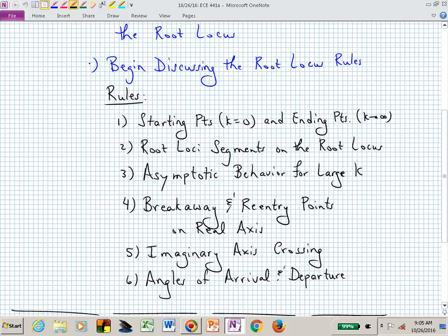Obviously, if branches go into the imaginary or into the right half plane, at that value of k, we're now becoming unstable. You'll have a homework problem where they go unstable and then you crank up the gain k and it comes back. So that's called conditionally stable, and it depends on how you tweak your adjusting knob on k. For some values it might be unstable, for other values it might be stable, then it might go unstable again. So it's very fun with adjusting this knob.